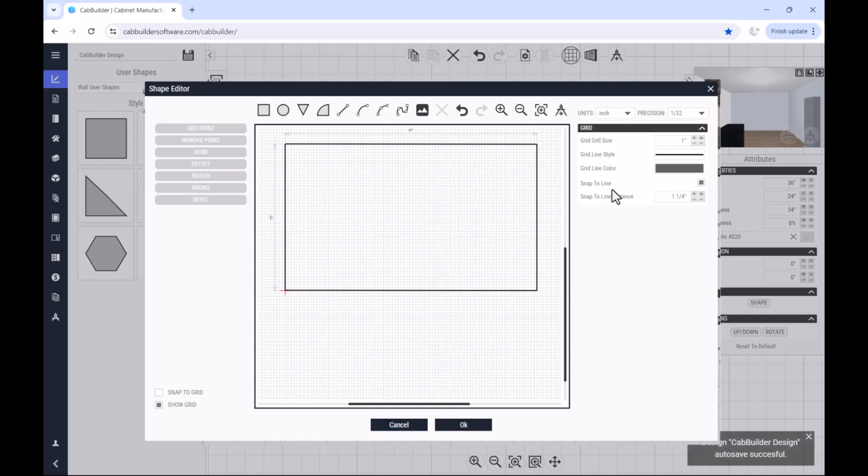This will then only attempt to snap a relocated line or point to an existing point in the grid space and provide the easiest way for the user to always create a closed shape. This is important to note because within the Shape Editor, you must create a closed shape in order to save the newly created shape with the OK button.